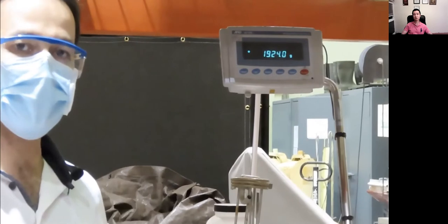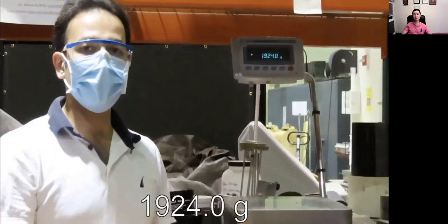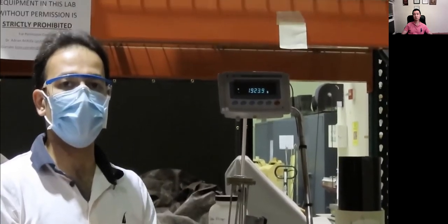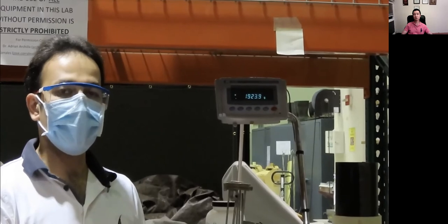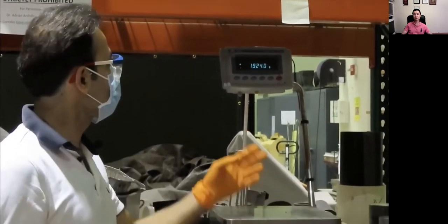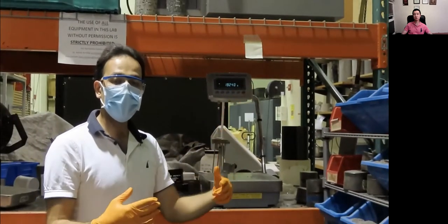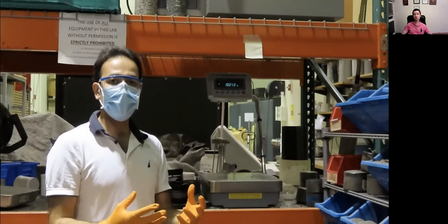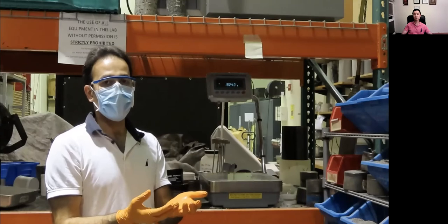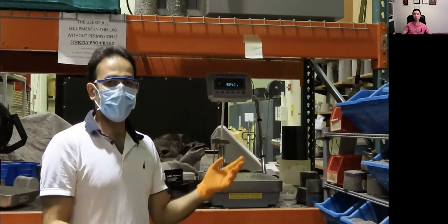The reason is that when we immerse something in the water, it's going to be lighter, equal to the volume of the material that we submerged in the water. In this way, we can calculate the volume of the aggregate, because the difference between this number and that 3,000 something is going to be the weight of water that displaced, equal to the volume of the material. So the difference is going to show you the volume of the aggregate.